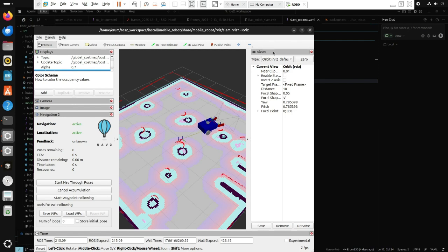So in conclusion, this project demonstrates the design and functionality of a mobile robot capable of manipulating objects using teleoperation, navigating autonomously, and interacting with the environment of a Gazebo simulation. Right now, the detection of the balls using the camera, giving its coordinates back, and moving the robot accordingly is not working. But currently, the camera works. It gives us real time visuals of the spheres within the assessment world. And it is also using the LiDAR data in real time, able to navigate autonomously within the predefined map.